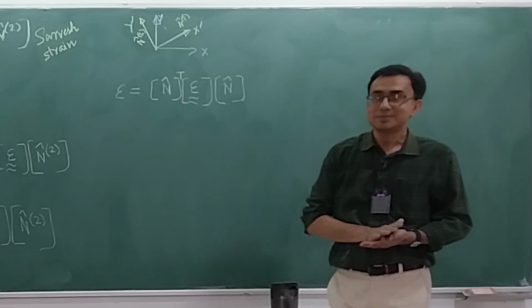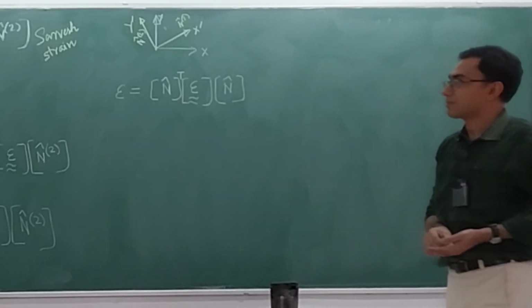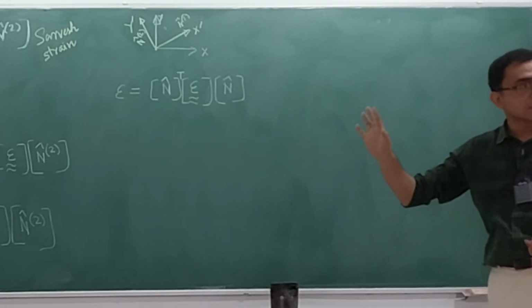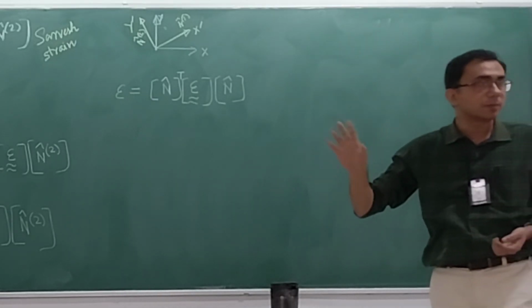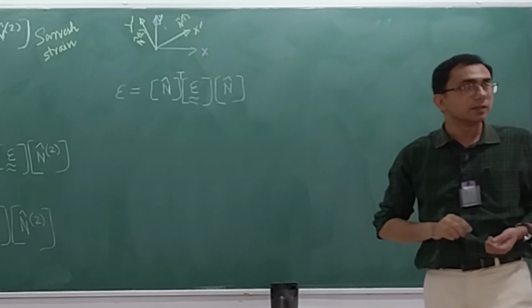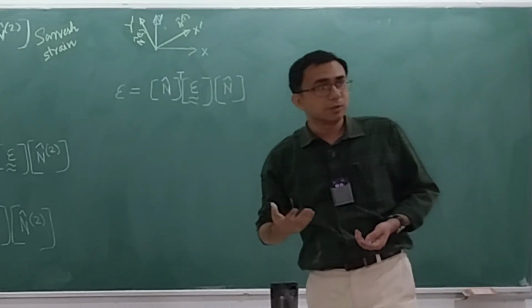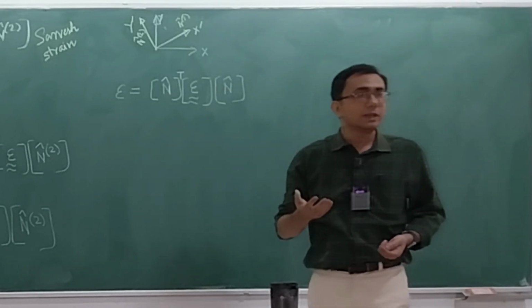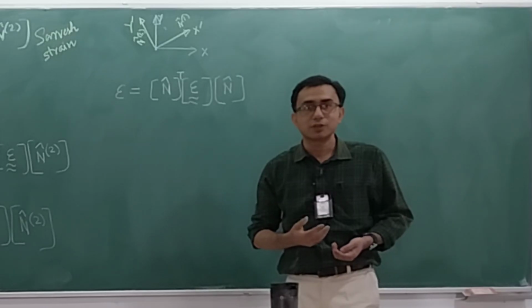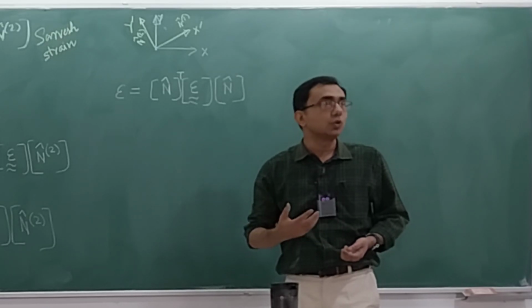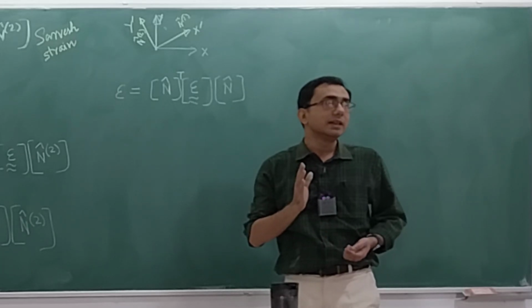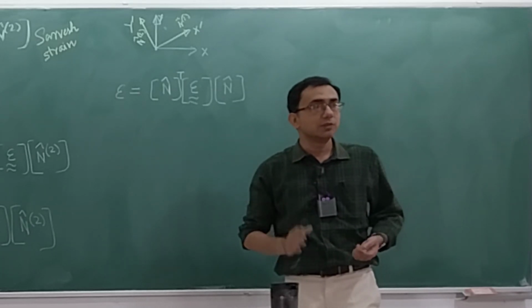But the official definition of shear strain has to do with two line segments which must initially be at 90 degrees to each other. See, this is the problem, right? If we all keep on defining our own versions of the strains, then we'll not be able to talk with each other. But once we fix it, that it is 90 degrees to begin with, then we are okay.